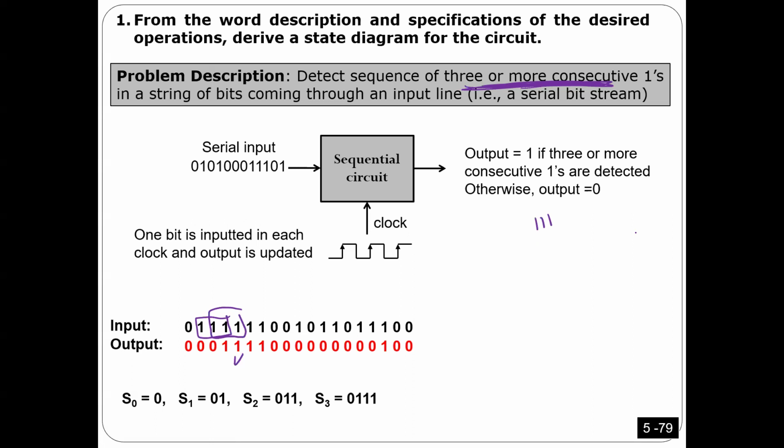If I ask you for 1, 1, 1, here what comes up is the point I explained about overlapping. So here you have 1, 1, 1, I will give you 1 here. But I need to have a new complete sequence in order to give you another one if there is no overlapping. But anyway, here what I'm saying is at least 3. That's why I got 1 here. The output here is 1 because the last 3 bits are at least 3.